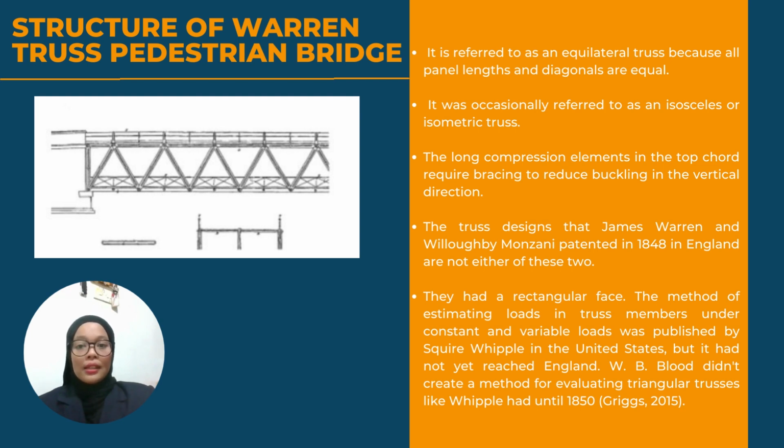The verticals in this instance are positioned from the lower chord panel point up to the midpoint of the chord member immediately above. Additionally, as the deck structure's length increases, it becomes necessary to either use heavier members or to add verticals from the top chord panel locations that descend to minimize panel length.